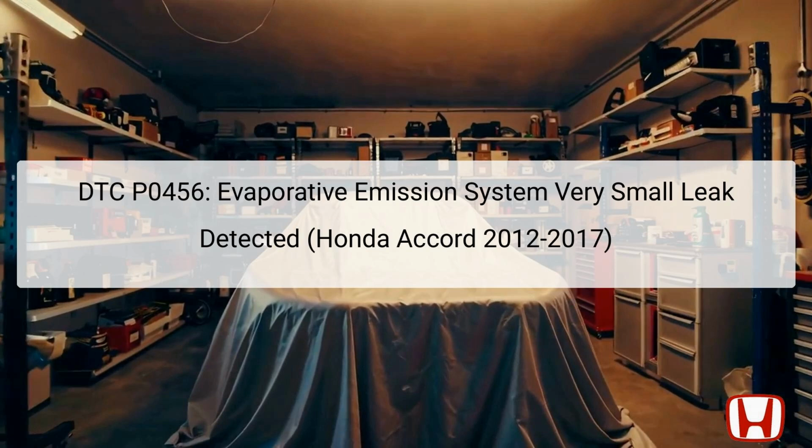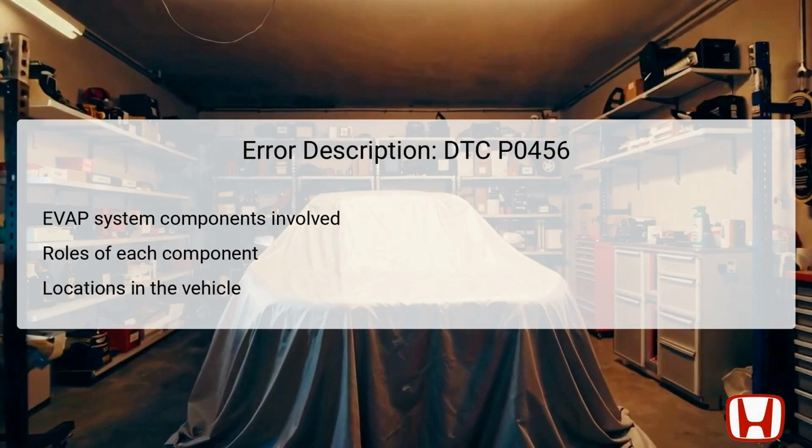The EVAP system utilizes an engine-off natural vacuum (EONV) method, monitoring for leaks when the engine is off. When pressure drops or does not stabilize as expected, it can trigger this code. Given the environmental regulations and the need for efficient operation, understanding and addressing this code is vital for maintaining vehicle performance and compliance.